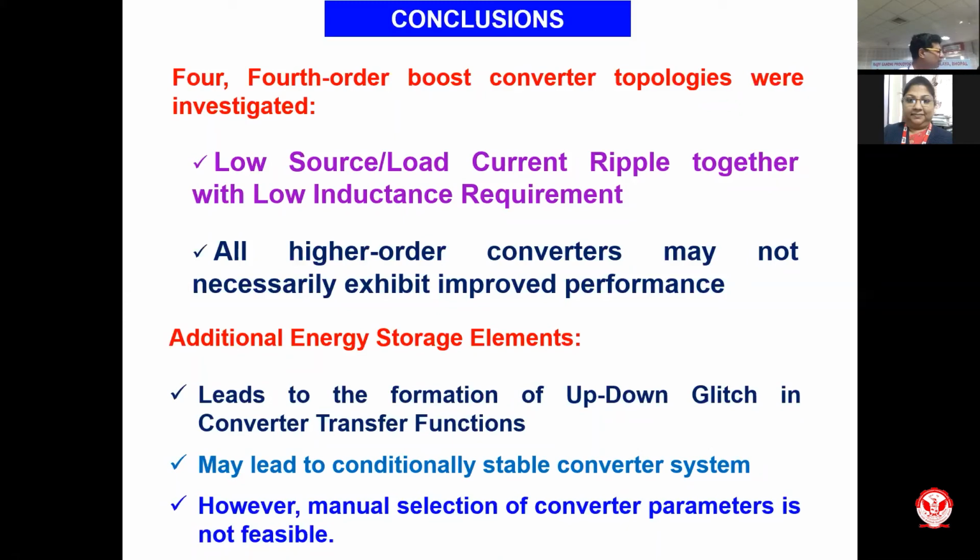But the key is that all classes of converters are available with a minimum number of energy storage elements, like your conventional ones. You may be well aware of a conventional second order bidirectional DC-DC converter as well. But again, the challenges we have talked about are still valid for those converters as well. So eventually you need to increase the number of energy storage elements, and in some cases you may need to even increase the number of switches as well as the number of diodes.